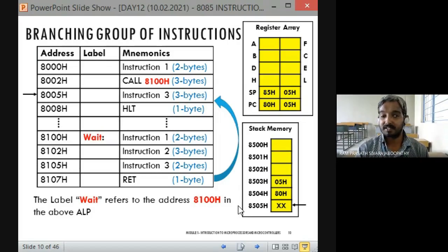Instruction 2 தான் கடைசியா execute ஆனது. அப்ப next instruction in the main program is instruction 3. That means whenever you use call instruction, it is going to the particular address. Before that, the next instruction address is pushed into the stack. Fine. In the particular subroutine, if we use the return instruction at the end, it will return to the main program by popping out the top of the stack values to the program counter.